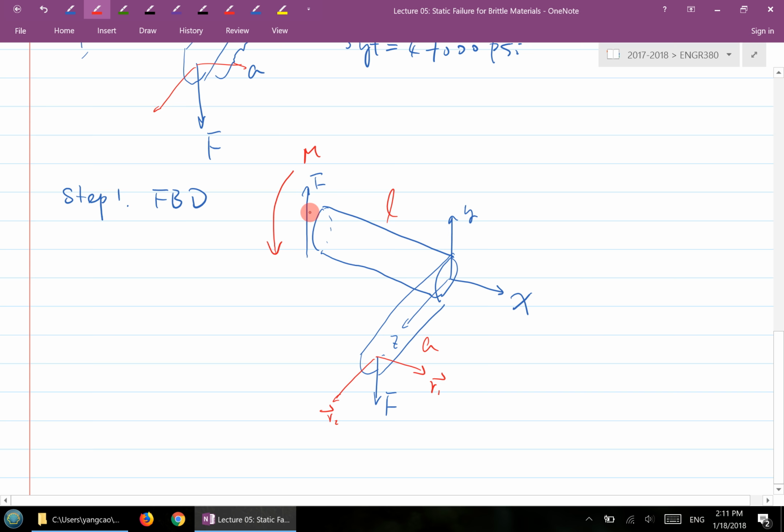Then on the wall, that torque should be what direction? From the wall side, it's this direction here. So to balance this torque, R cross F is trying to rotate it this way, so you have a counter torque to balance it out. So you have a T here from the wall.